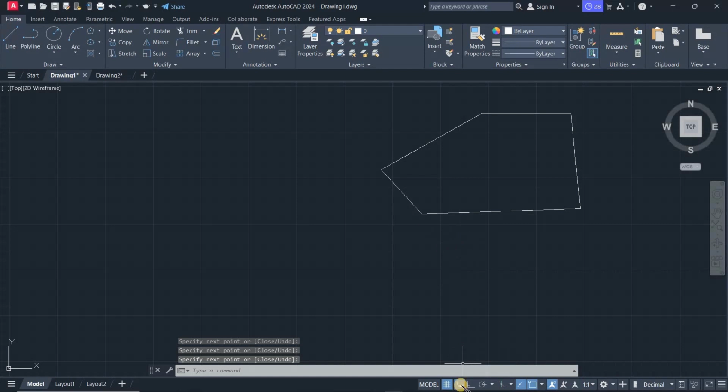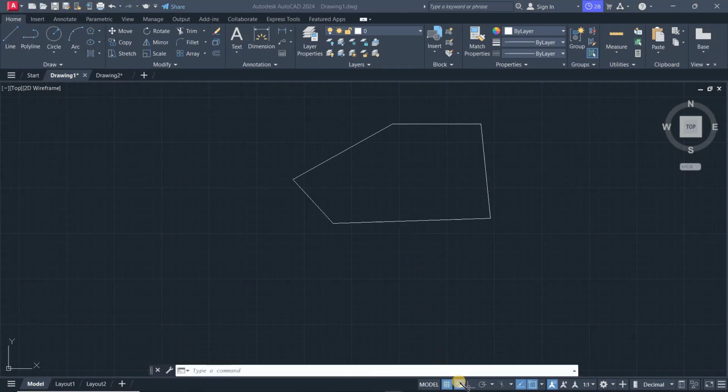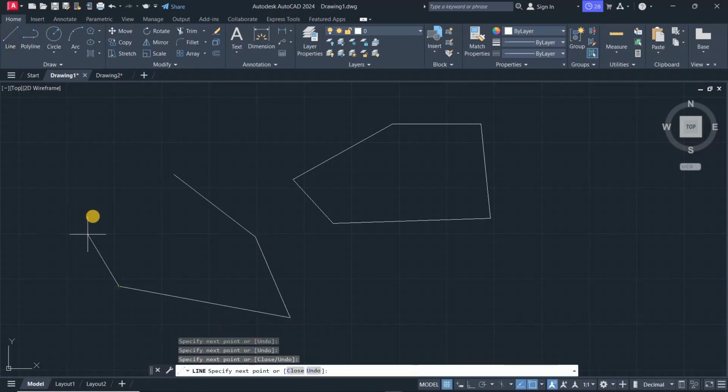So you can influence a setting by click rather than having to go through the settings. Notice that if I disable this dynamic input mode and then choose to draw a line, let's say I pick a line and start drawing, there's nothing specifying the length of the line I've drawn, neither the angle that I'm about to. And then if I right click, I press enter.